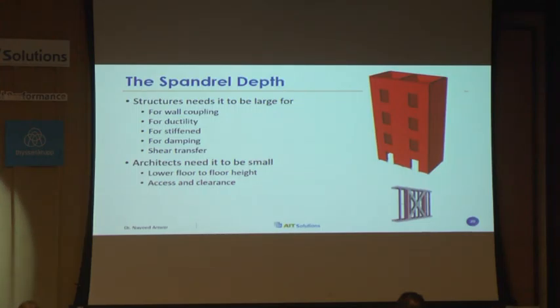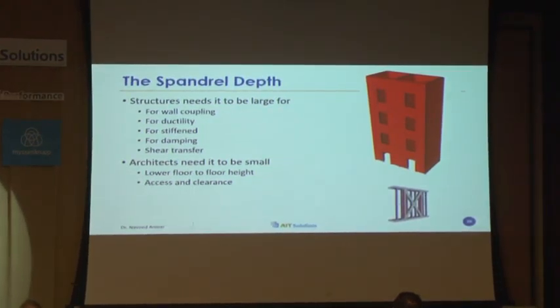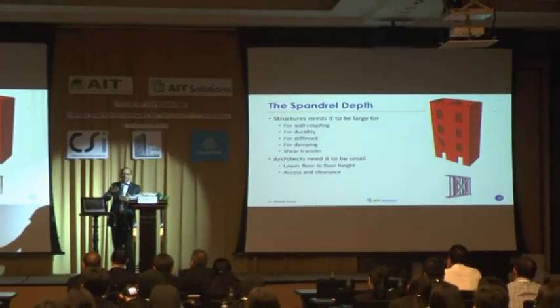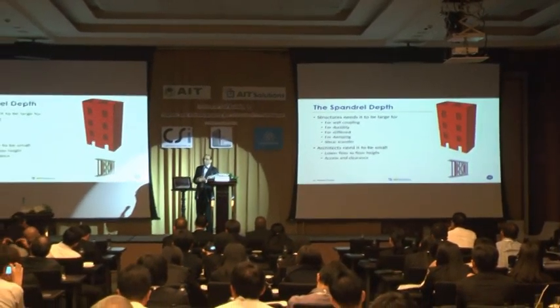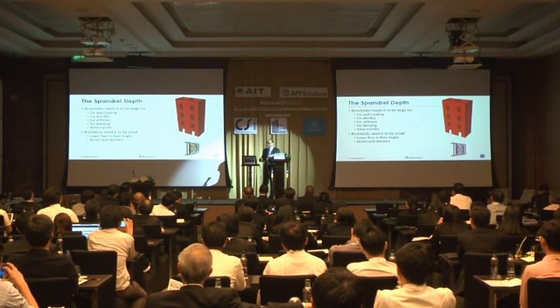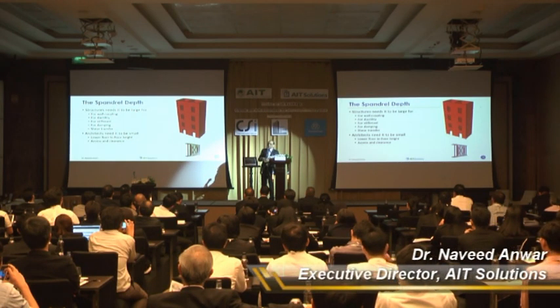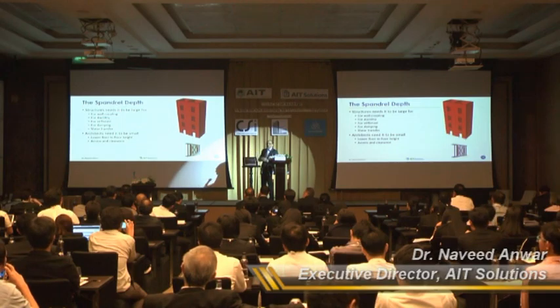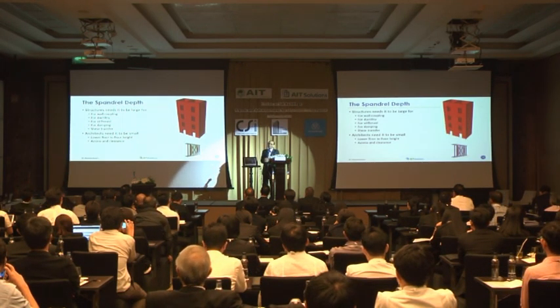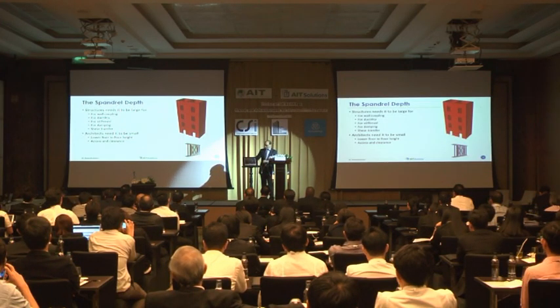And this spandrel, you cannot change the height because there's a door beneath that. You cannot change floor height. You cannot change the core wall thickness, it won't be allowed. So then you put steel diagonals there, you try many things, and people have come up with special spandrels, and I think, Boise, you're using them on some projects, right? Yeah, so these specialized devices. So spandrels are becoming more like energy dissipation devices rather than members of the core wall. So this is another challenge that you will find in the design of the core wall.